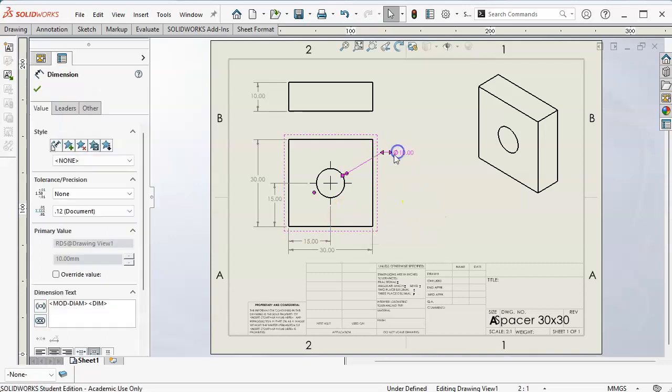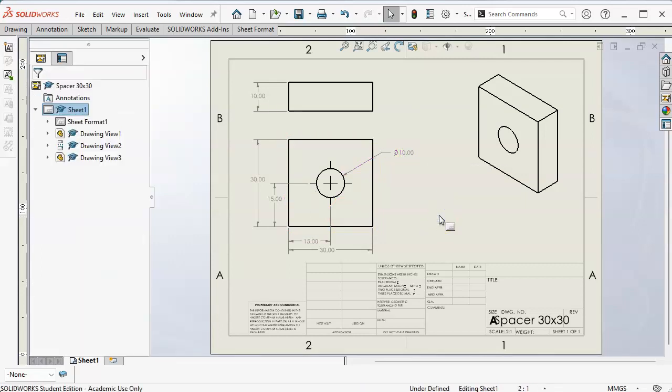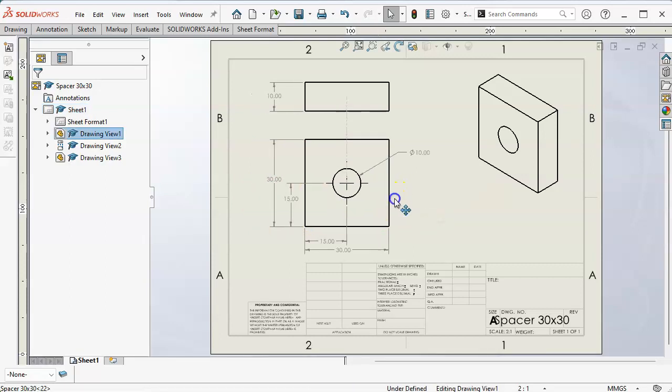Instead of a straight leader, I get the bent leader. It's just preference. If the drawings get tight and there's a lot of vertical dimensions, then having that dimension aligned with the extension line helps. I kind of adopted that when I was doing the casework, and a lot of the line boring generated a ton of dimensions off of that side.